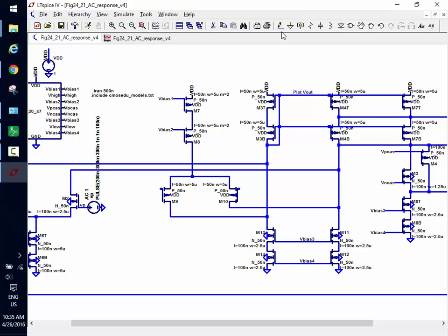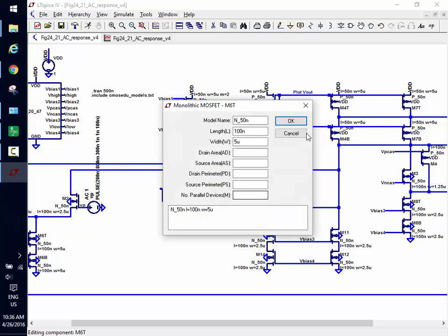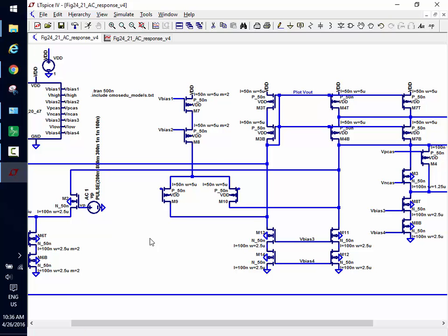Let's say that I'm biasing up and both of these are right at VDD over 2, so both the NMOS and the PMOS diff pair are on. Does everybody follow that? So I've got 10 flowing through here, coming in, going down through here, 10 flowing through here. Remember, let's be consistent. Let's call these 2.5 and 2. And just to be consistent with the other, 2.5 and 2. Does everybody follow that? And so I've got 10 flowing through here, 10 flowing through here, then flowing through here. I got 10 and 10.